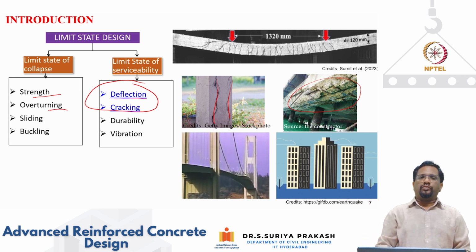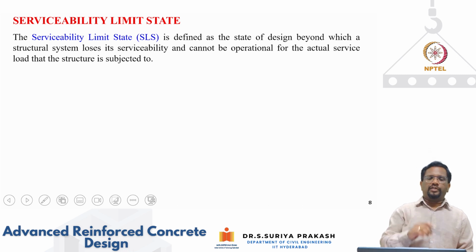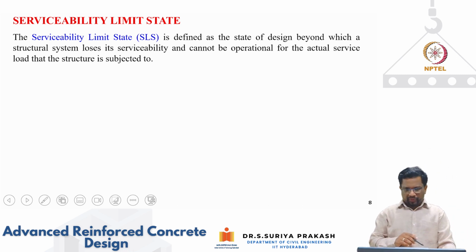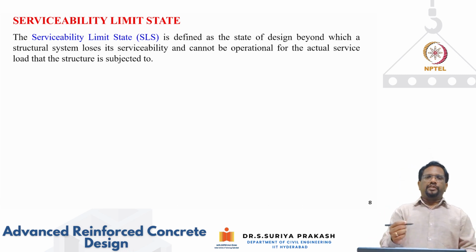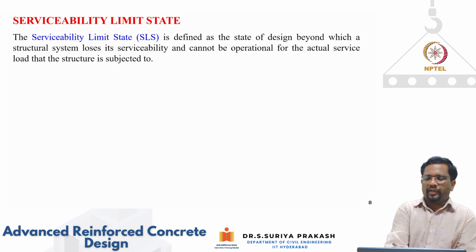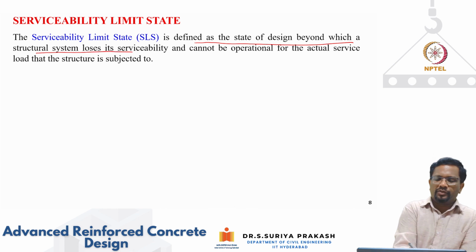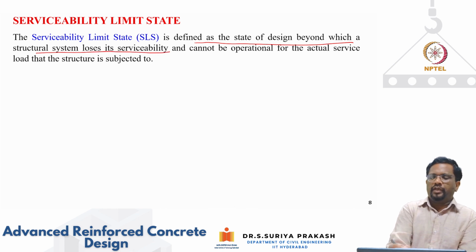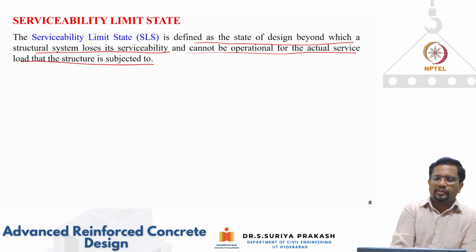We are going to focus on the two most important things in terms of limit state of serviceability. Those are deflection and cracking. Now let's see what the serviceability limit state is. As the definition says, serviceability limit state is defined as the state of design beyond which the structural system is going to lose its serviceability and cannot be operational for the actual service load that it is subjected to.